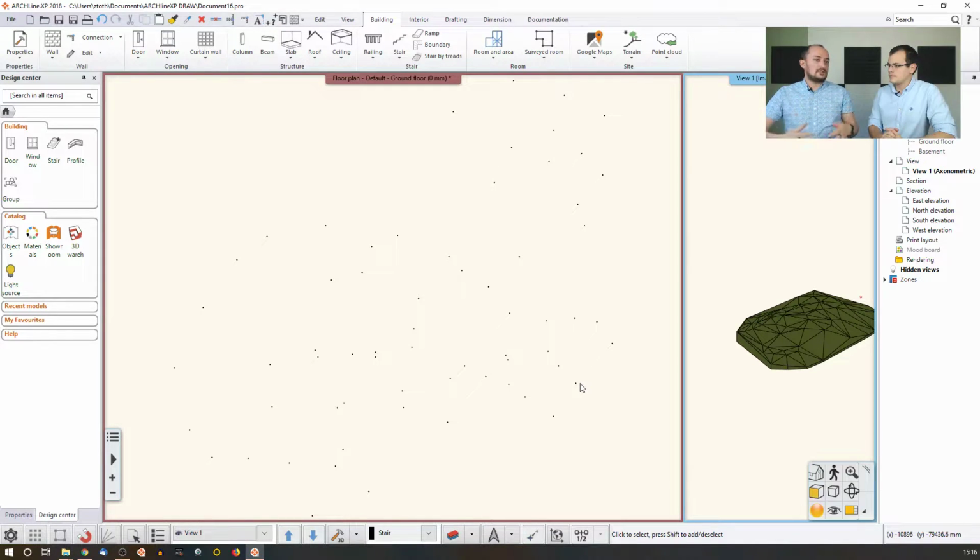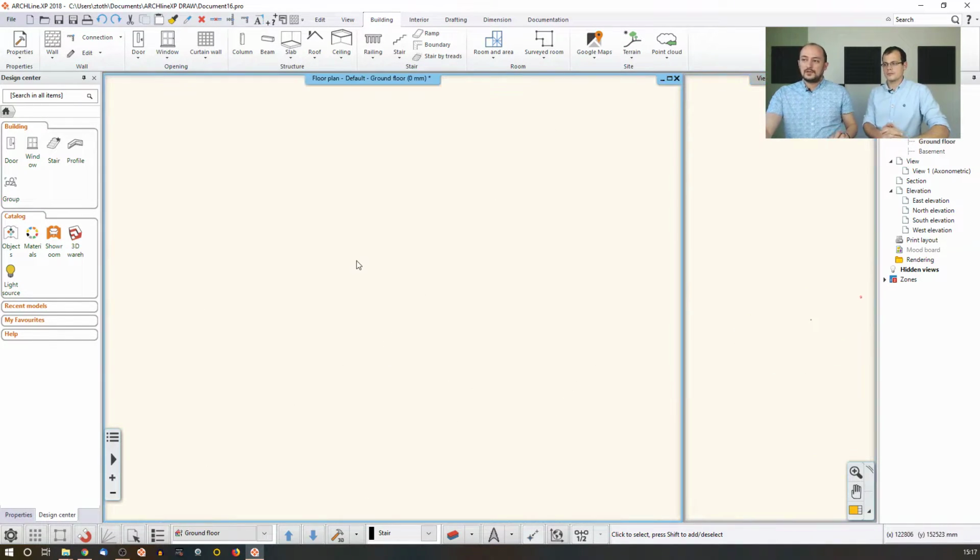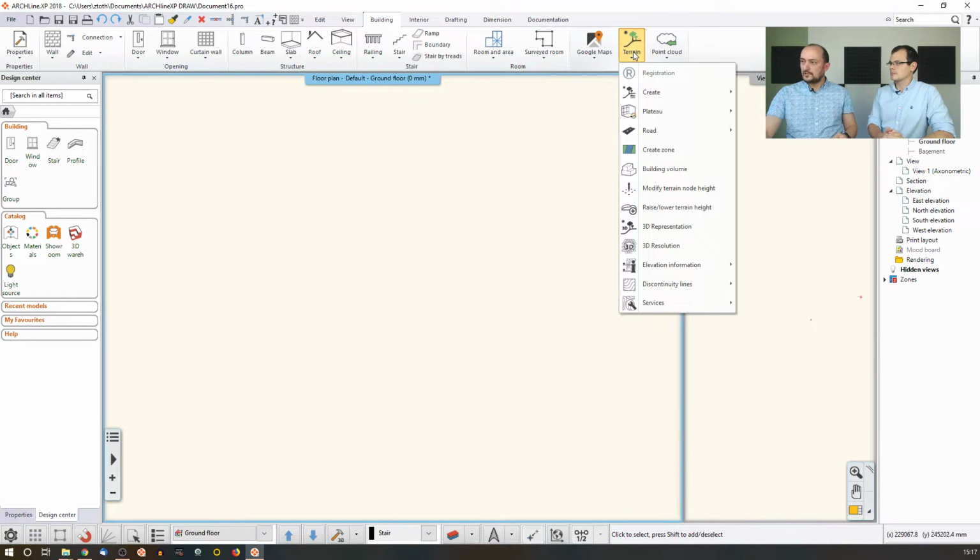I can make changes. I can recolor it. Do we need to scale these? Not this time, because when I load these sort of file formats, the software has the size information in. It's not only the coordinates like number 1, number 2, and 1 point something and 1 point something. So it is already scaled properly. The one issue could come if you import a DXF file, for example, which is not a big issue. You just need to know about that. Just one extra step. Yeah.